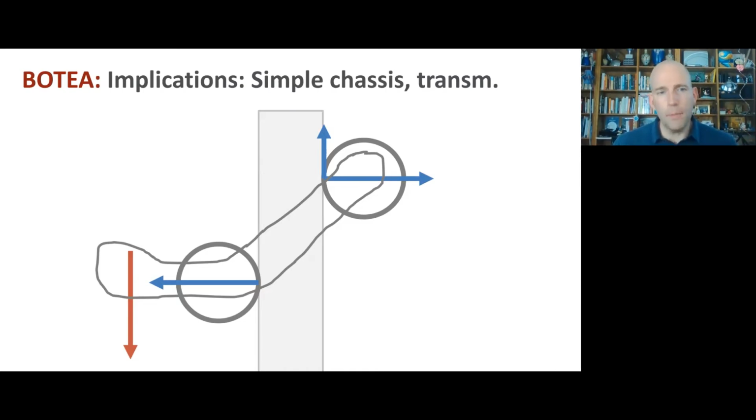Furthermore, by having one drive point, we wouldn't need a complicated transmission to connect, say, this wheel down to this wheel, so that can make our transmission and connections to the motor simpler. So this is the direction that I went in designing this. I know some teams chose alternate paths that also worked out well. But this was my thinking, to try to keep a simple structure and avoid a complex transmission.